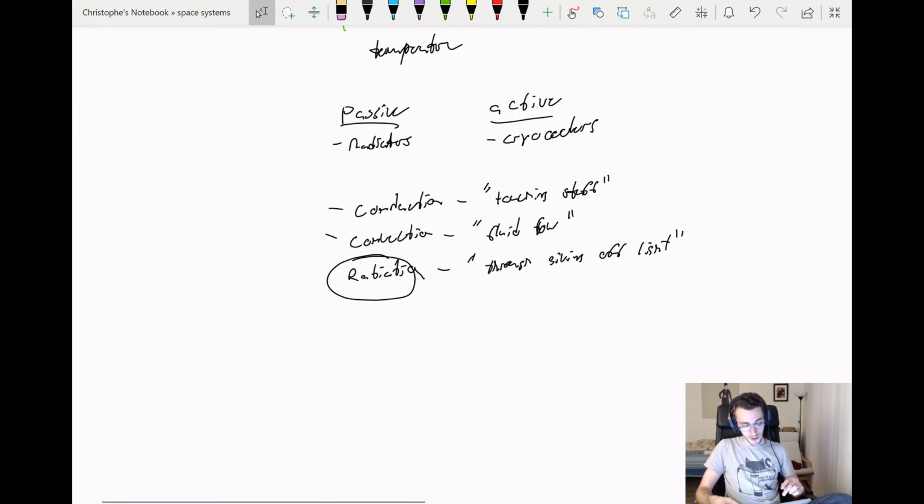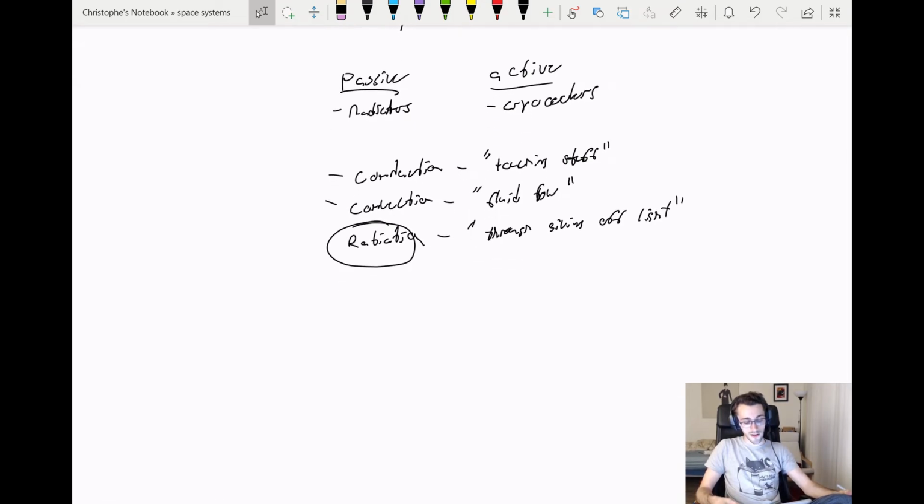So with radiators, that just increases your thermal emissivity, so you give off more heat by electromagnetic radiation. The downside with those sorts of radiators is that if you're scanning the night sky and you knew the thermal signatures of the satellite, it makes it really easy to find your satellite. It's kind of easy to find based on launch points anyway. But if you didn't want anyone to know your satellite was there, you might want to be careful about how your satellite emits heat and where. So you might want to have it on different parts of the satellite.